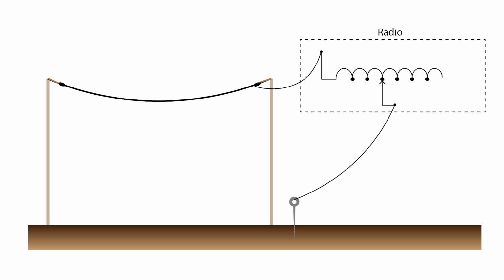Okay, so that takes care of the inductor. But where's the capacitor in this circuit? It looks like there isn't one. Well, actually, there is. The antenna and the earth effectively form a capacitor, with the antenna forming one plate and the earth the other. However, we, of course, have no control over the value of this capacitance other than perhaps choosing a suitable length for the antenna. So this does limit our ability to fine-tune our LC circuit.